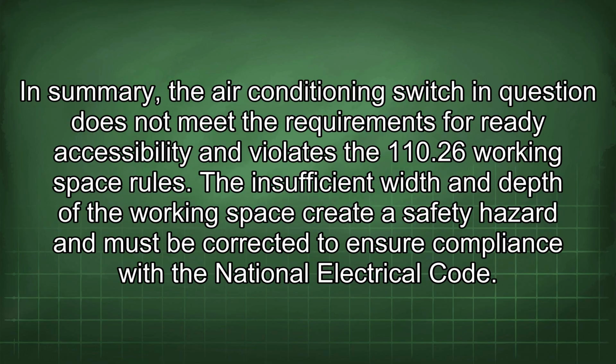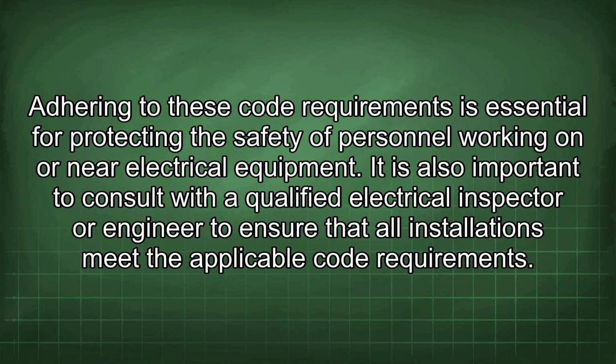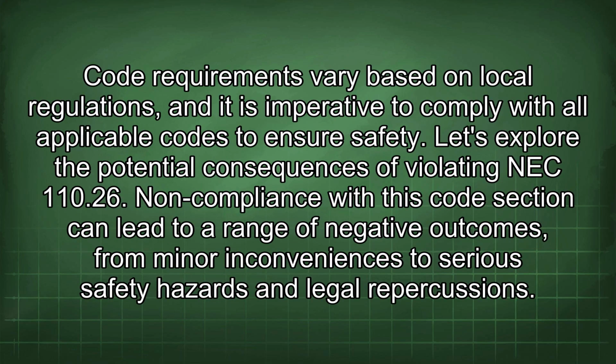In summary, the air conditioning switch in question does not meet the requirements for ready accessibility and violates the 110.26 working space rules. The insufficient width and depth of the working space create a safety hazard and must be corrected to ensure compliance with the National Electrical Code. Adhering to these code requirements is essential for protecting the safety of personnel working on or near electrical equipment. It is also important to consult with a qualified electrical inspector or engineer to ensure that all installations meet the applicable code requirements. Code requirements vary based on local regulations, and it is imperative to comply with all applicable codes to ensure safety.